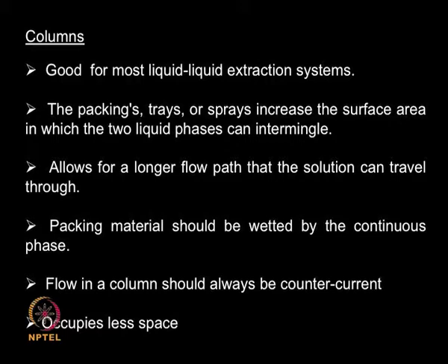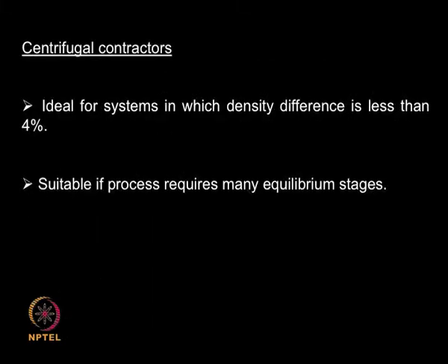But one important point is the packing material should be wetted by the continuous phase. So, you cannot have a very low flow rate such that the packing is not wetted at all and there are some dry regions, because then you are not efficiently making use of the packing. Generally counter current is preferred because you get better separations or better efficiencies, and of course as I said it occupies less space as well.